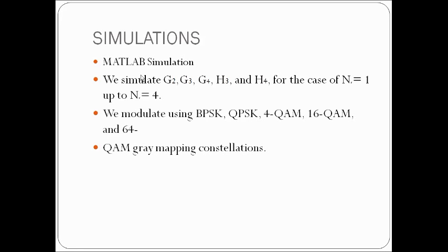Blocks of 100 symbols are simulated until 10^5 bit errors are generated. When SNR reaches 40 dB, the simulation is stopped. Another criterion to stop the simulation is when 100 blocks are simulated without any errors. A confidence level of 99.9% is achieved for a BER of 10^-7 with 100 errors.